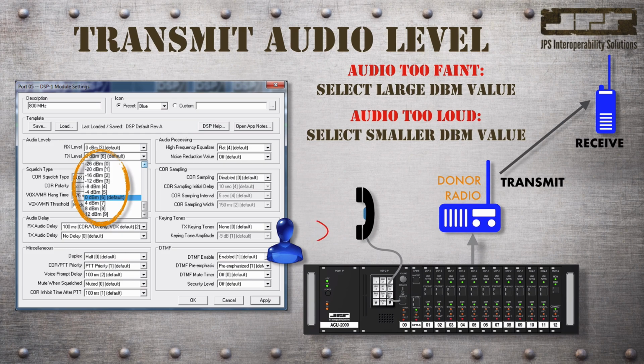And once again, if you're uncomfortable with using dBm values, simply use the unitless numbers within the brackets as a volume control or gain control. Lower numbers within the brackets mean that the audio heard by the field radio will be more faint than the larger numbers within the brackets, just like a volume control. Again, the alignment using just the ACU handset is adequate in most situations.